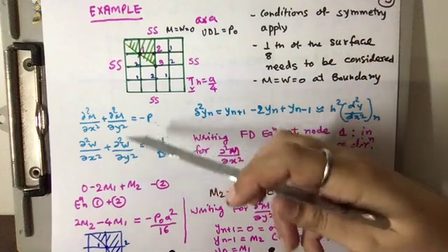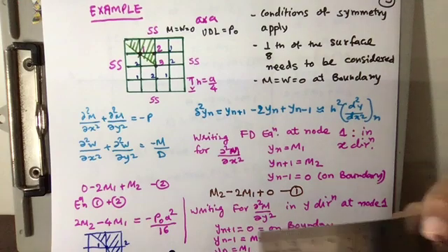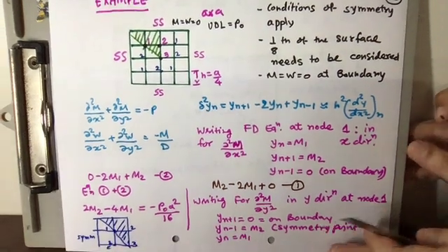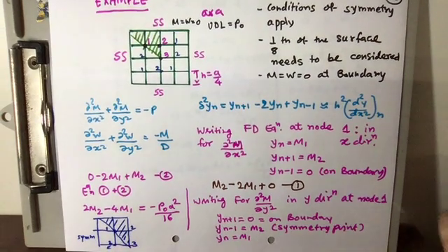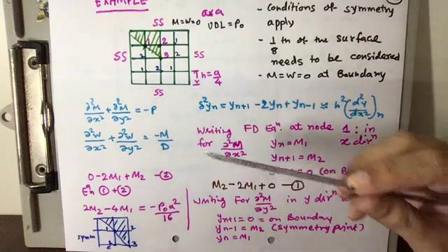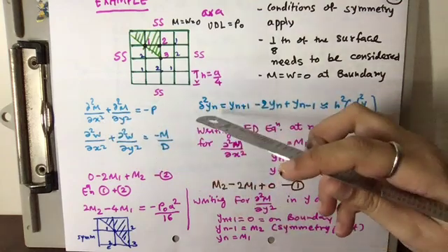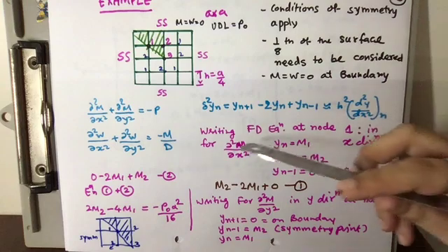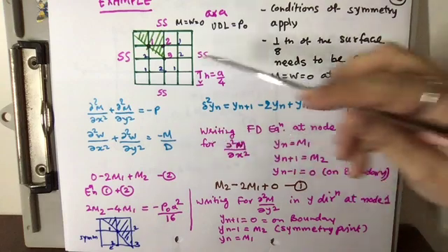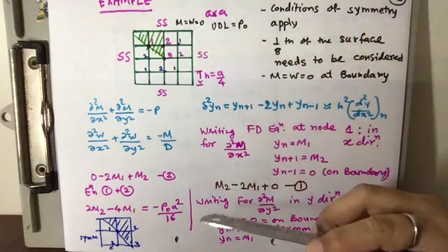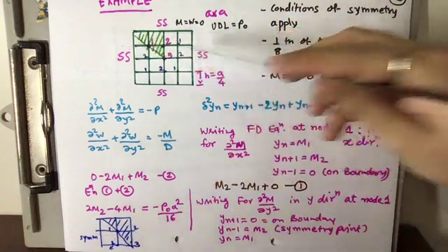So we start with this partial differential equation simultaneously because this is easier to solve. Why is it easier to solve? Because it's second order, simple. So writing this first equation, this is our original second order differential equation in finite difference form. Now writing the finite difference at node 1 here in the direction x. Okay, node 1 in the direction x.